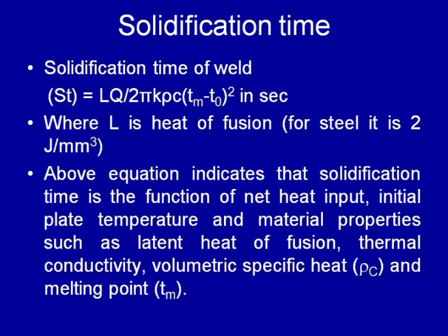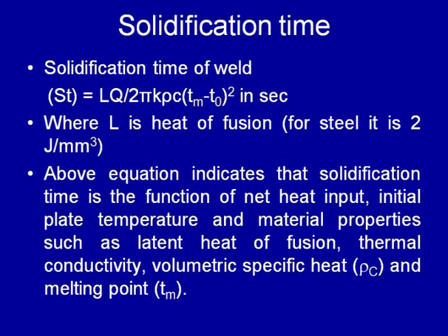The above equation suggests that if we increase the heat input, that is the Q, then the solidification time will increase. Or if we increase the initial plate temperature, then this entire quantity in the denominator will decrease, and this decrease in the denominator will increase the solidification time. So, these two aspects can be easily observed from this equation: an increase in heat input and an increase in initial plate temperature both will increase the solidification time.